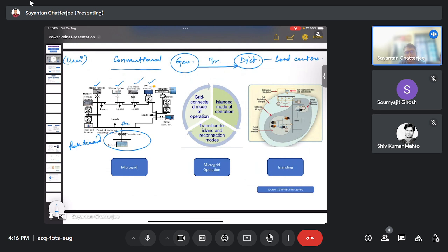We have discussed that peak demand can lead to a frequency drop, and a frequency drop can lead to an under-frequency problem, which might lead to desynchronization of the synchronous machine. So we have to maintain the frequency at the correct value, and for that we always try to have backup or spinning reserves available to meet sudden peak demands, and these peak demands can be met using the microgrids.